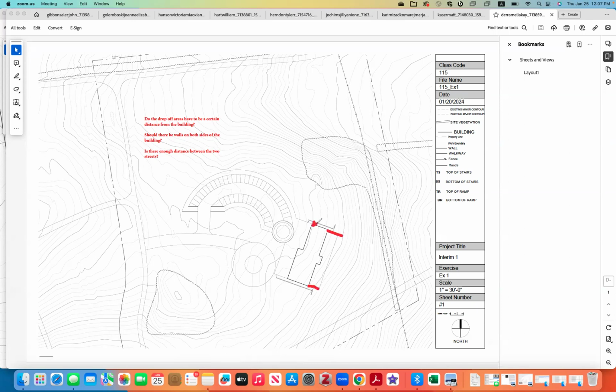Because in that space you can fit a stair. You could have one stair in it. You don't have to have two stairs on both sides. So one of the retaining walls will be here. If you have stairs there, the retaining wall will be there, and then you will get rid of that line. But on the other side, your retaining wall will be a continuation of your building wall. Okay. So I was going to place the stairs on the top because there are no contours, and then do the ramp on the bottom. Yeah, that makes a lot of sense.